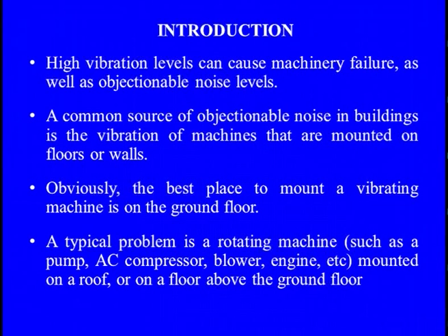A typical problem arises when we adopt machines like a pump, compressor, AC compressor, blower or any kind of engine that we need to mount on a roof or on any floor above the ground floor. Because of the rotating elements in these components, they cause high levels of vibration.